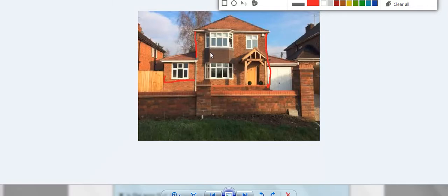So they are your heat loss walls, and let's assume that the back is fairly standard, there's no conservatories, etc. on the back. You can also see from this property that you've got a tile hung area here. So clearly from a technical perspective, we know that that bit's going to need to be part of our calculations when we're looking at how much of the property we've actually treated. We're not interested in the garage because let's assume that the garage is going to be unheated, therefore that remains your heat loss wall.